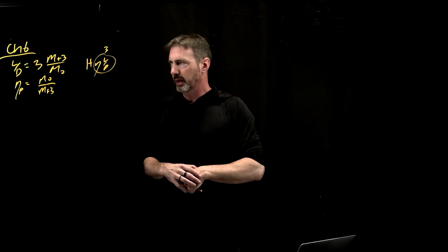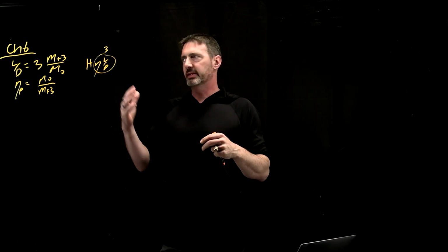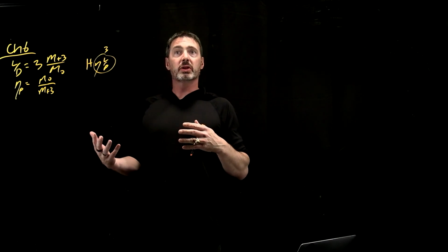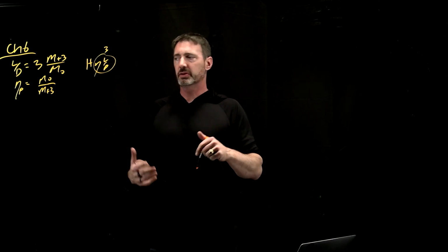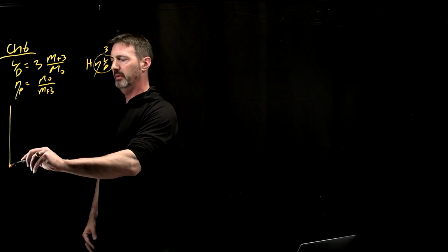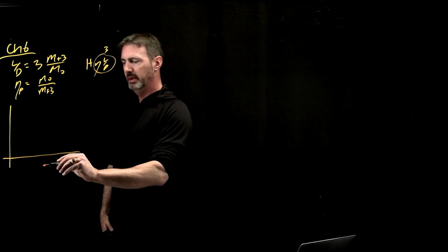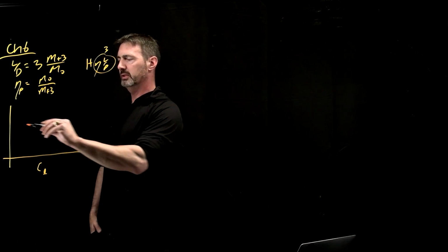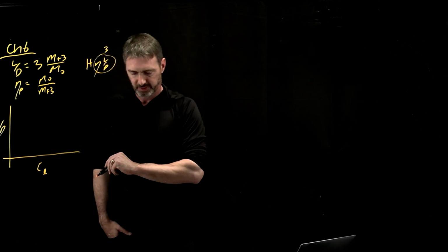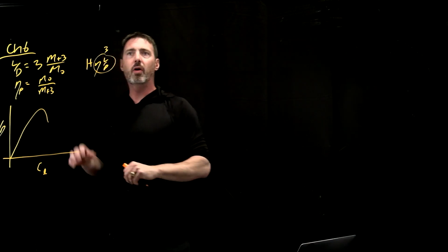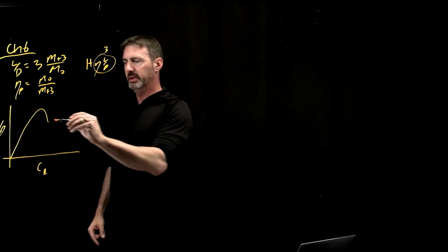Okay. The other piece in chapter 6, this is really all about slender supersonic aircraft. He really does a good job of showing the challenge, the biggest problem you have to solve for, and this is plotted as lift coefficient versus L over D. You're going to have something like this, and this would be stall, but this is at your cruise condition.